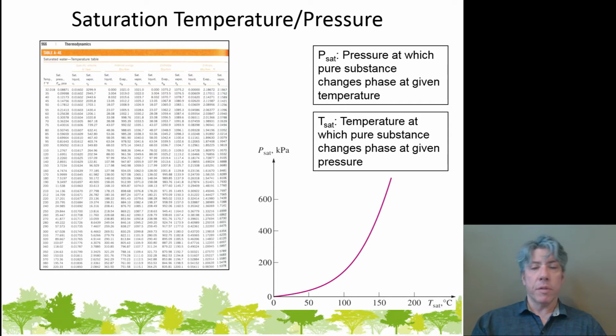It's 212 degrees Fahrenheit or 100 degrees Celsius. We all know that. We've learned that a long time ago. But if you change the pressure, if you somehow put the water into a container that can be sealed, and you can evacuate some air out of it, or you can pressurize it, say with more air, that would work fine, then you will change the temperature at which the water boils.